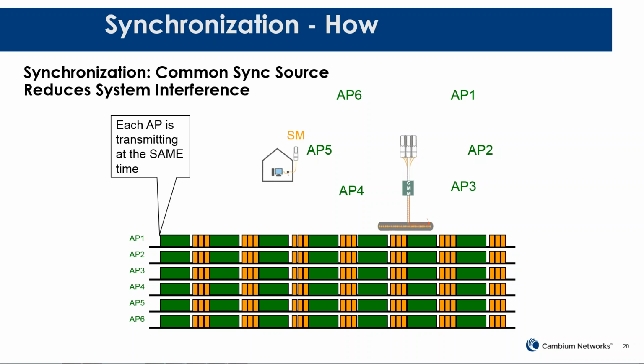It is not network time protocol, where you're sending a protocol that's telling you the time of day, the date, things like that. That is nowhere near the precision needed to synchronize radio duty cycles or transmission cycles. It's not a 1 pulse per second type of protocol. So please, when we say a synchronized timing signal, we don't mean NTP. That is simply used to provide time of day to devices, mostly for correlating alarms and syslogs so that everybody has the same time of day. If you have problems, you can correlate alarms and events across your network from a single time source. Does that answer the question, I hope?